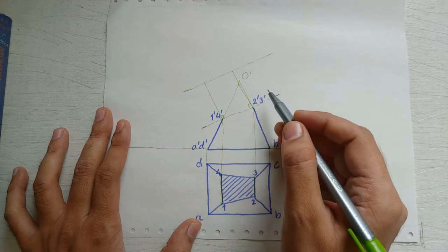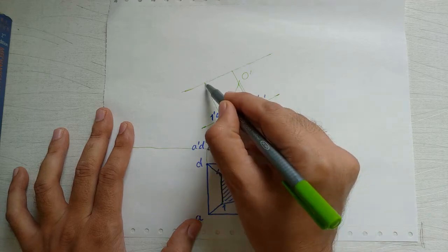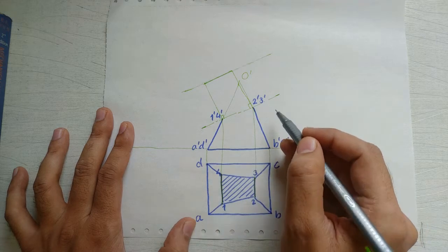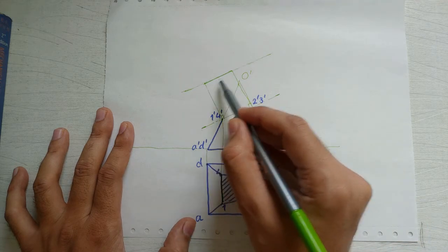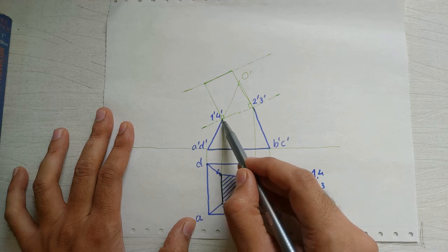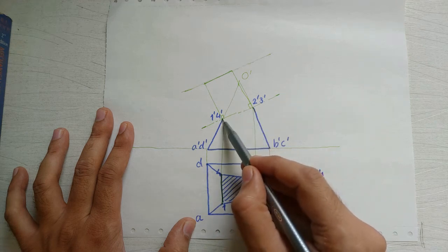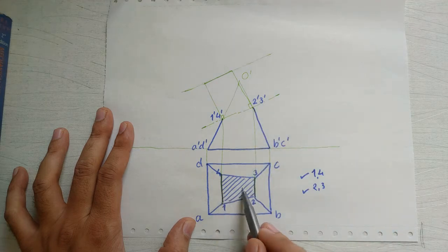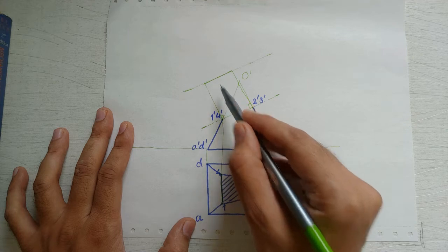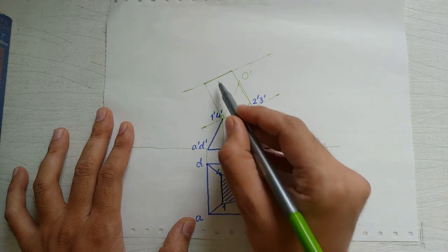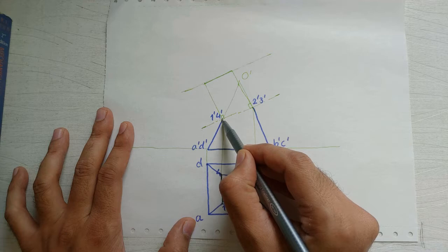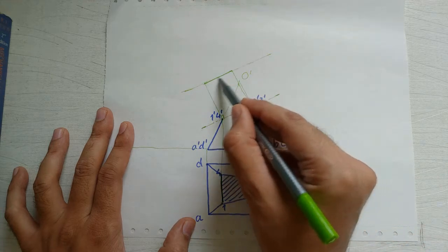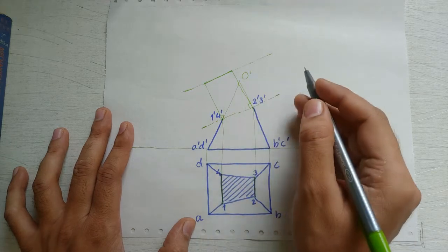Now we can see that we have obtained, if I look at this particular length, that is the true length between these 2 points. Okay, so that is what we wanted. We wanted to draw the true length of this. So if we draw it like this, first we'll draw a parallel line to this, and then we'll take projections from 1 prime 4 prime 2 prime 3 prime. We got that required length here now. So true length we have.